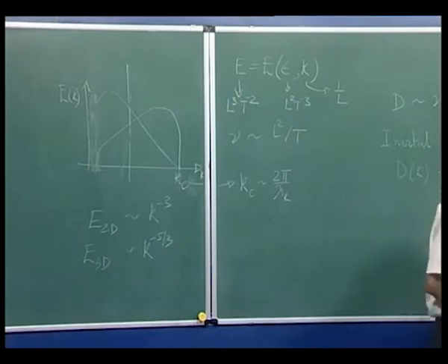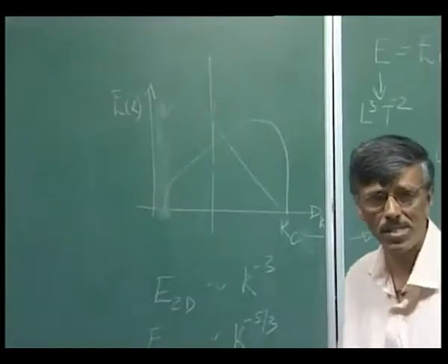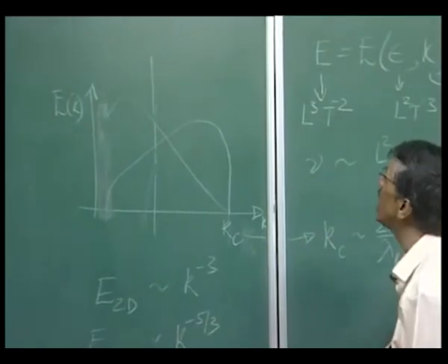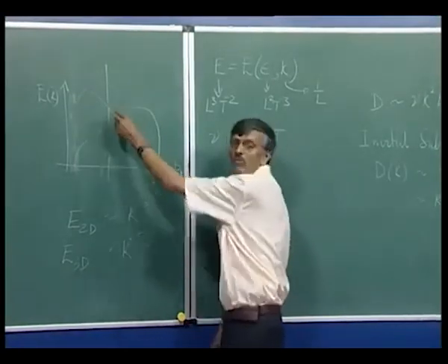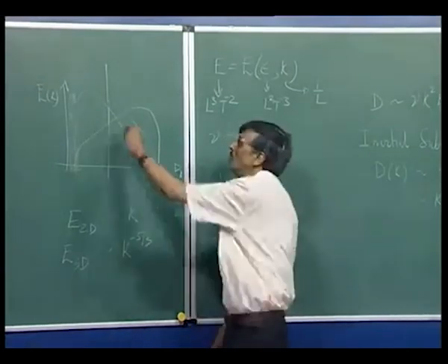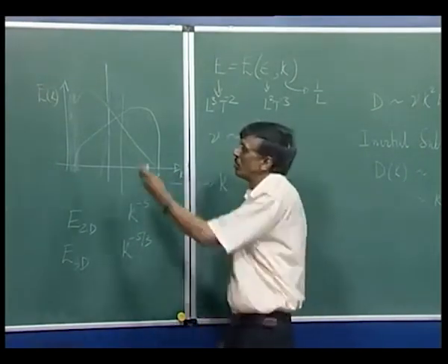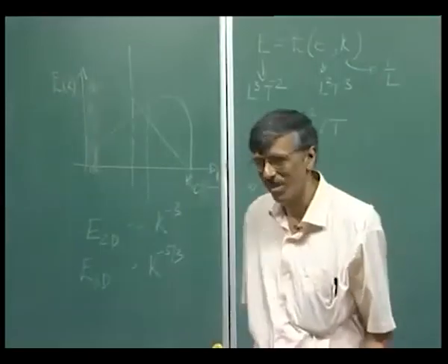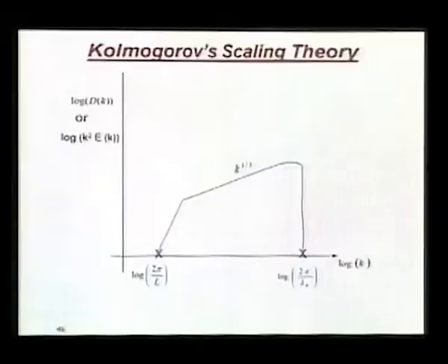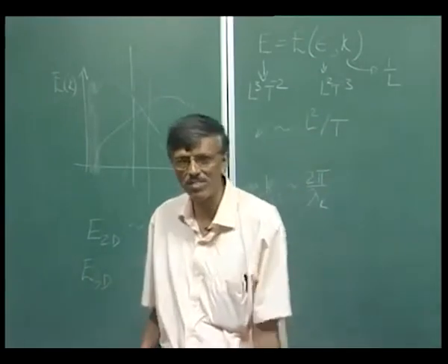So, you see, this is important in computation, that people tend to think that I will do LES and all I need to do is worry about E of k. I will short circuit this E of k somewhere and I say, oh, I am doing it. But people do not talk about what they have to do correspondingly to the d of k. But the d of k has this structure, and d of k is more important maybe in the scale which is beyond this. So, that is at your subgrid scale.